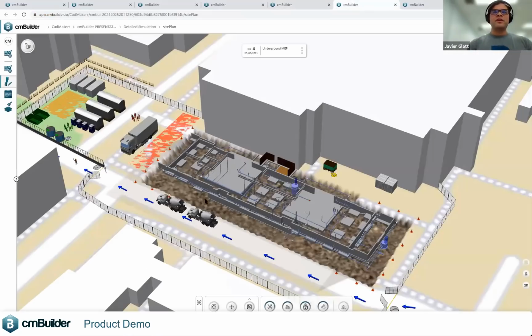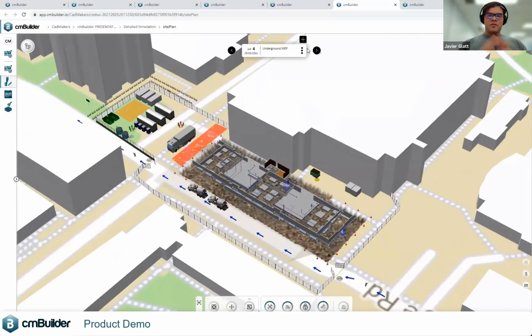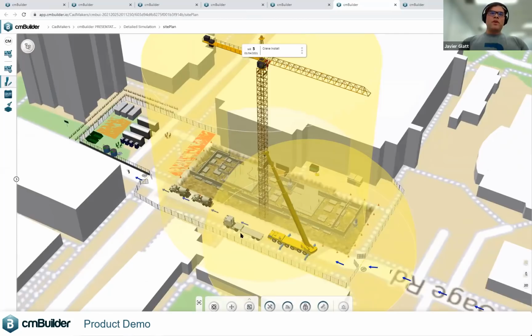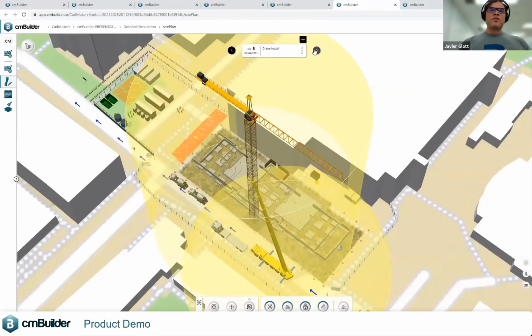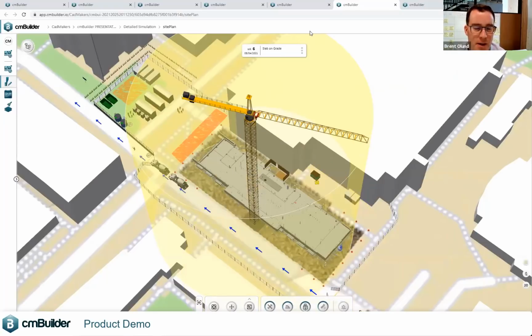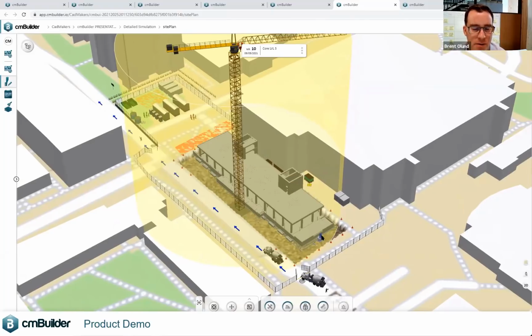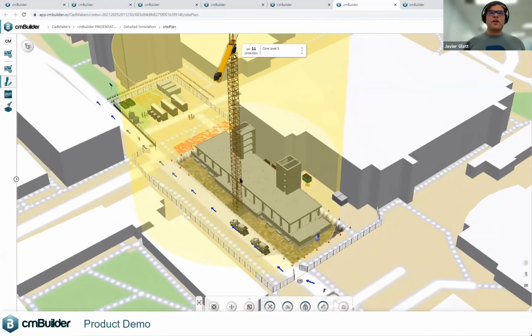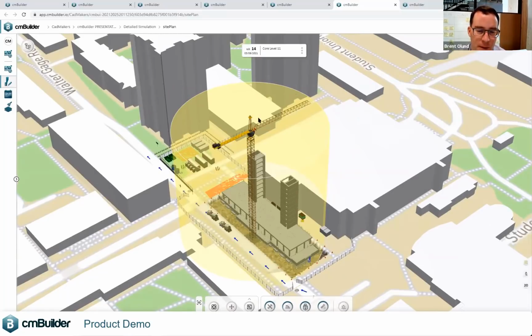Let's go back into the 4D scenario here. So now we're going to go to, Brent, we're going to talk to you pretty much Brock Commons. The goal was to build the concrete and the cores in the winter months, from what I understand. Roughly, what was it, about 4 months, from bottom of the ground? 4 months, yeah, around 2 months in the ground up to the podium, and another just over 2 months to build the cores. Right, so we've started to simulate that. That was with 2 stories at a time jumping form system that we had to come up with. Normally, the cores would have gone more slowly than that by about a month.